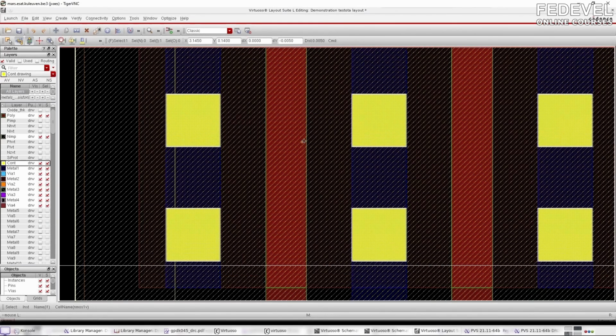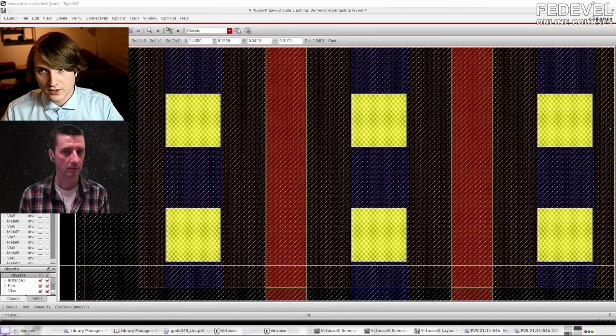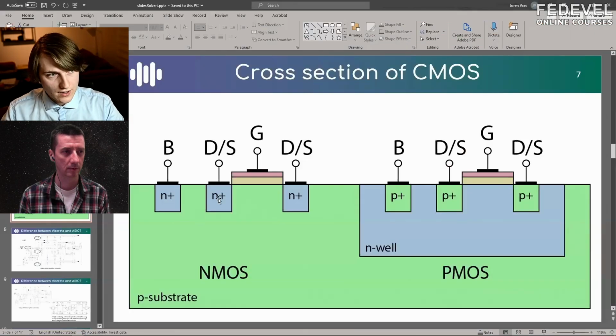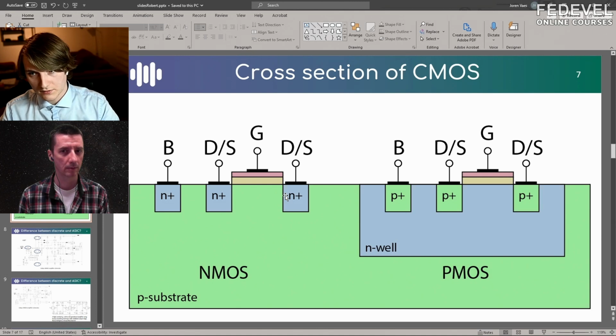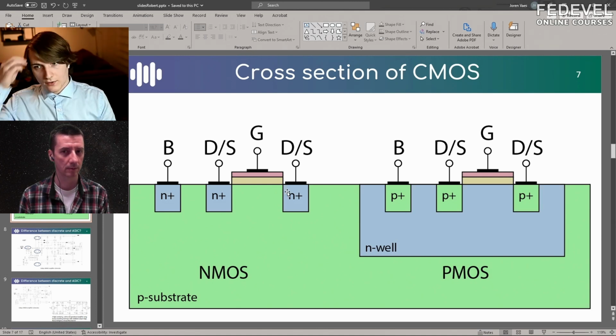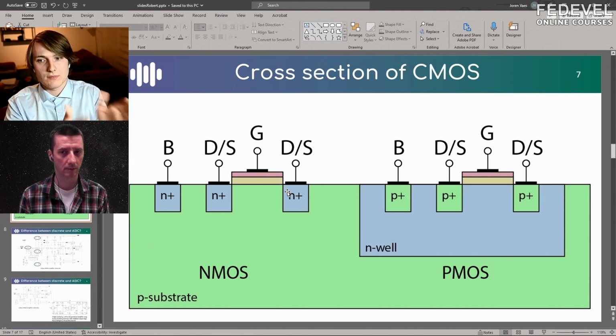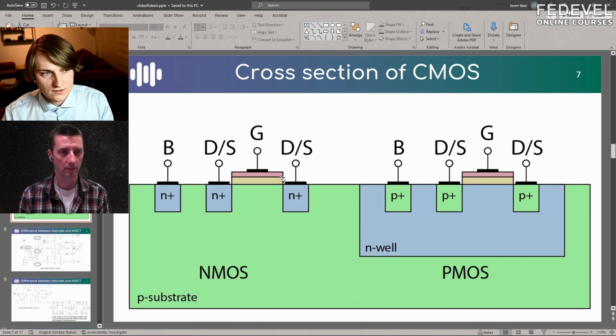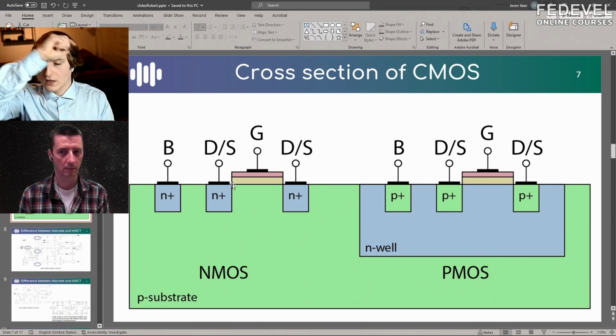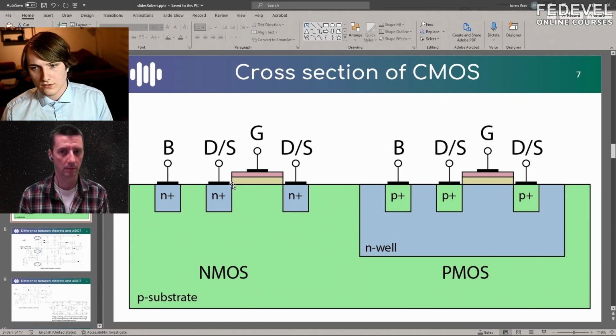And the gate length is kind of a determining factor in the analog performance and density. So to map that to our 2D view from earlier, it's the distance from here to there. That's 45 nanometers. And so up to about 20 nanometer bulk CMOS, that was actually the physical dimension that they make. So at the 22 nanometer technology, this distance is at least 22 nanometers. Or you can always go bigger, but you cannot go smaller.